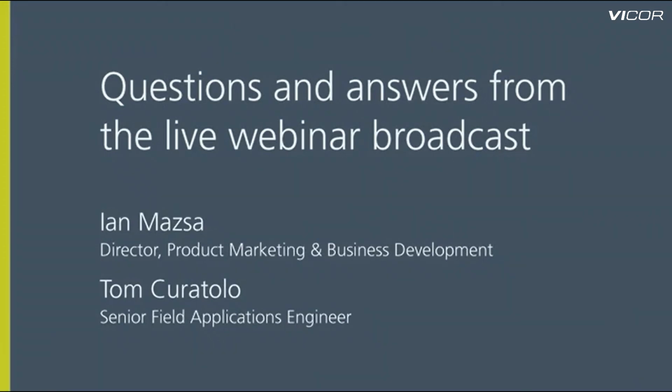Sure. Also on the website, we talk about some future products and some capabilities. In that same size and the power level that I talked about before, that's 6135, kind of 80 amp capable, we have the ability to increase that input voltage range all the way up to 1200 volts for the same kind of BCM capability. So the K factor would probably be a little bit higher, maybe 1/24 to get down to a cell level. I personally have been in meetings and heard customers even ask about 1500 volts, but that's been primarily with solar panel arrays and not so far with drones. But I'd be just curious if that was coming about or if people saw a path to higher voltage or not.